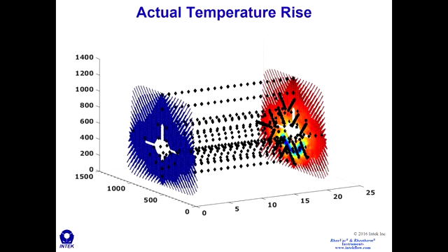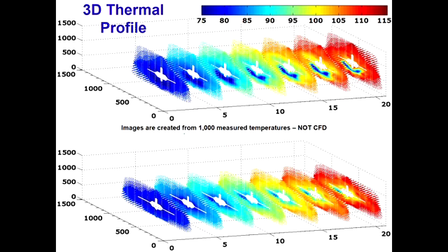What these black dots are here is a Westinghouse condenser where we've installed instruments inside the tubes and on the outlet tube sheet. And the black dots represent a location for each and every temperature sensor in this study. And so we've been able to create a complete three-dimensional model of this particular Westinghouse. And here are the temperature profiles using this technique.